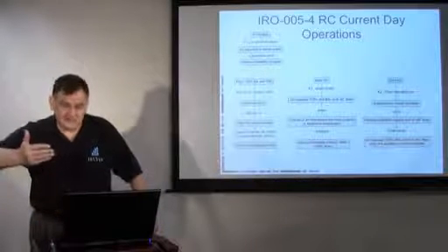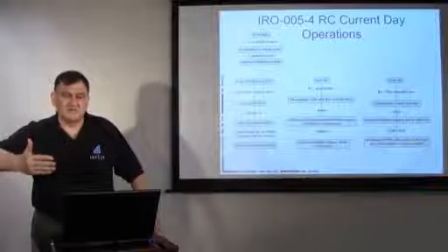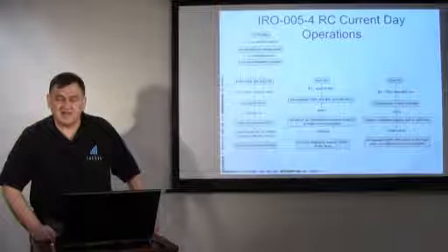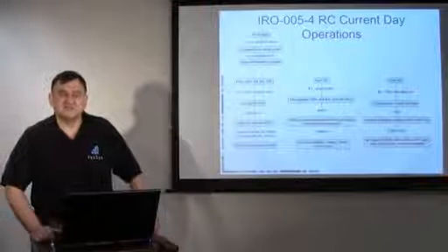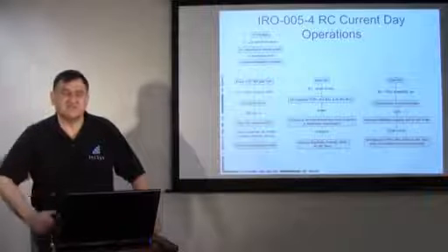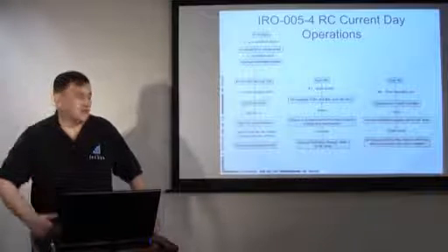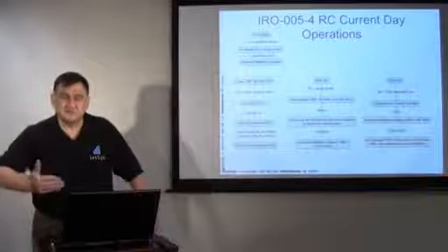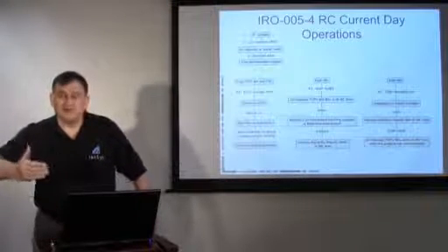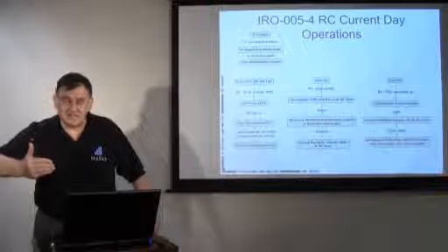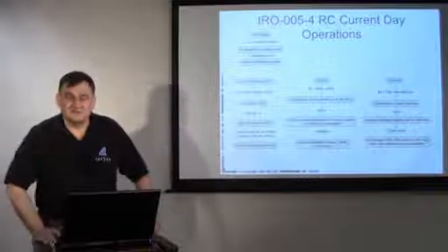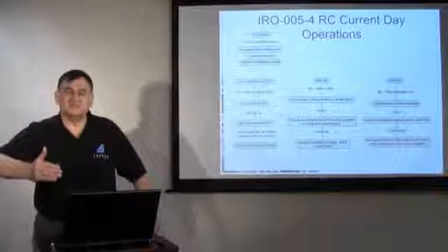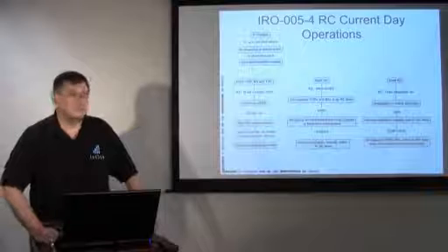And so again, it's that discipline of being willing to say, look, we're going to run our system so that in the event that any single contingency happens, we will be secure, we won't have a cascading outage. So there's a whole process of taking those violations really seriously and being willing to spend the money to run the more local, more expensive generation usually to be secure. If you don't do that, the consequences are evident. We saw this with the 2003 Northeast outage and the Southwest outage. So really, it's an educational process to make sure that all the entities take those violations really seriously.